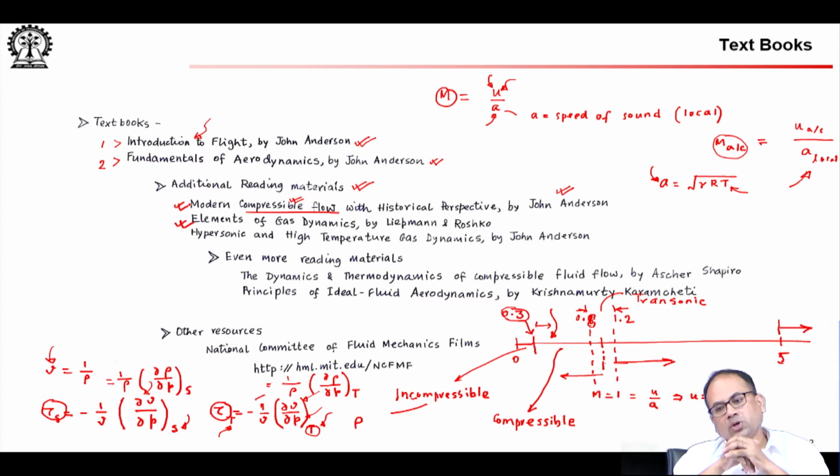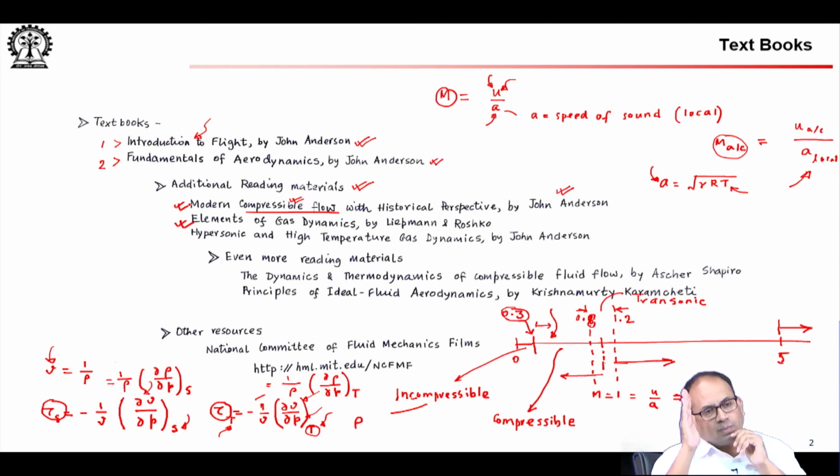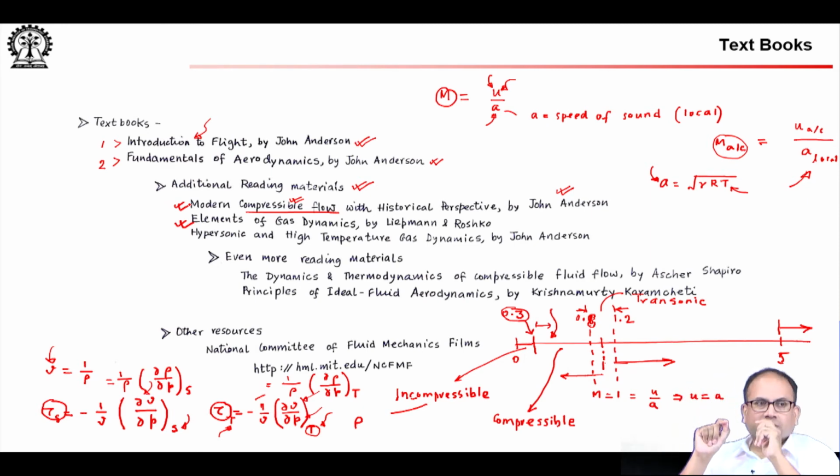So, you will first hit say Mach 1, Mach 2, Mach 3, and you see that the shock wave angles are gradually decreasing and things are changing, but around Mach 5, which is not a very tight boundary, sometimes it can be Mach 4.5, sometimes Mach 5.5, sometimes as late as Mach 6, some very distinct aerodynamic phenomena start showing up.